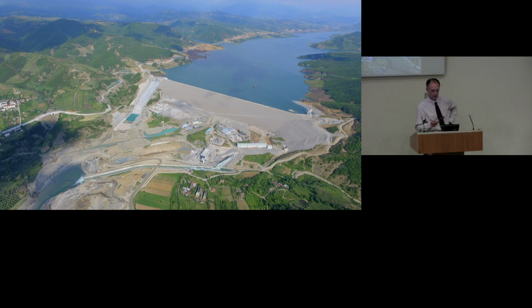We had great sympathy with the contractor, but also with the designer. One of the difficulties was we suggested that they did some works much further up the slope, to get drainage works in, get the water out of the slope, and manage the water better. I haven't talked very much about drainage. There was a battle really to get the contractor to manage the water well, but there were things we could have done further up the slope which would have helped. And of course, that was a problem because you couldn't instruct the contractor to do works outside of the construction site. There was a contractual issue there, and we didn't have access to the land.